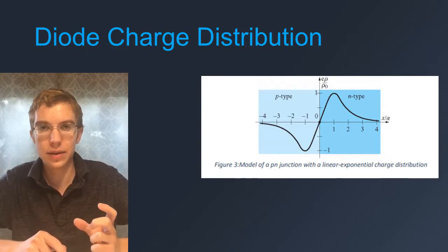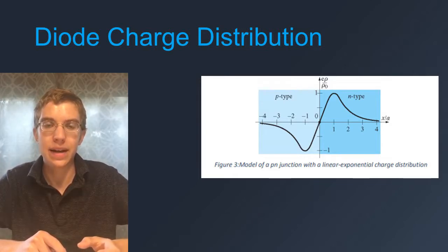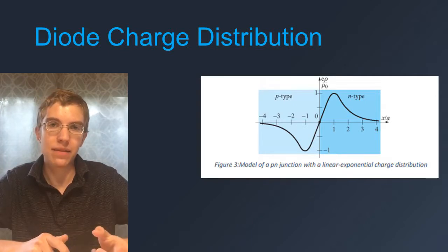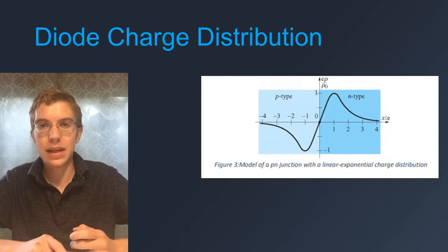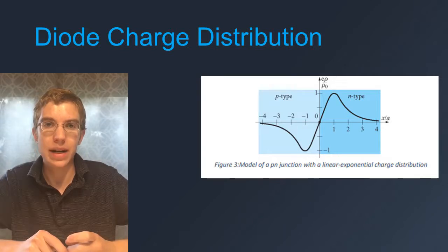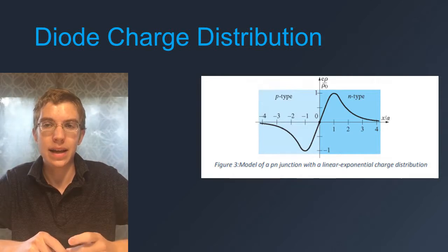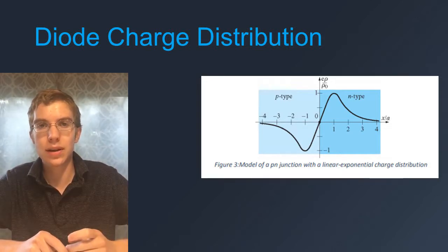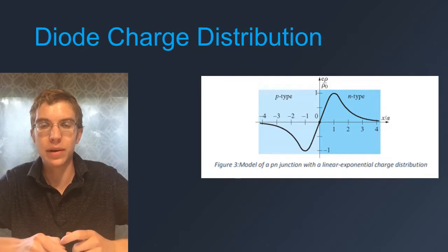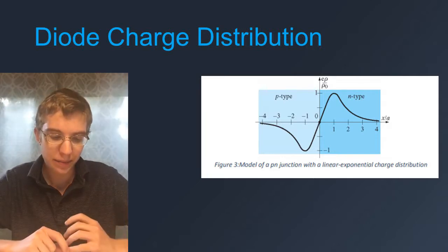And so if the threshold value is higher, obviously the electric field in the depletion region is also going to be higher. This means that the work that needs to be done against the field is going to increase, and that manifests itself in a couple of ways. We'll see the amplitude of the rectifier output decreased by twice VD on, and then we're also going to see a delay from when the source turns on to when the rectifier is producing an output. This is because the source is increasing its voltage, but it hasn't met the twice VD on level, so the output is still 0.